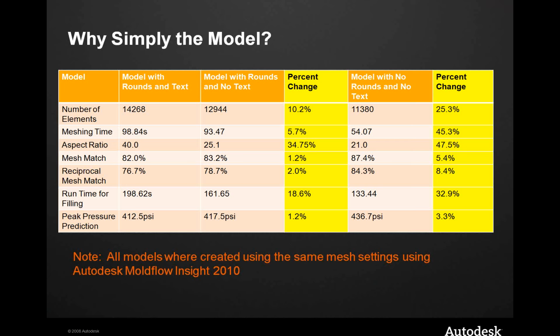The same thing holds true if I start to take off some of those tooling rounds. Again, now I've got a 25% decrease in my overall mesh count. I've got just as accurate a representation of my file, and I have created a more efficient model that I can now simulate inside of these packages.